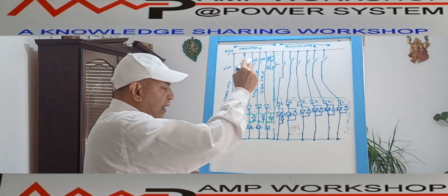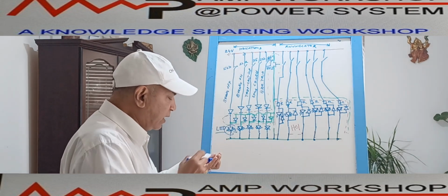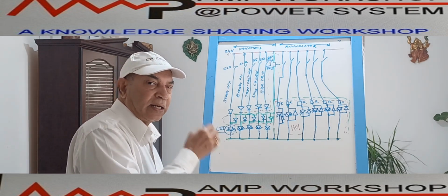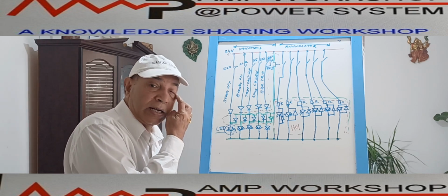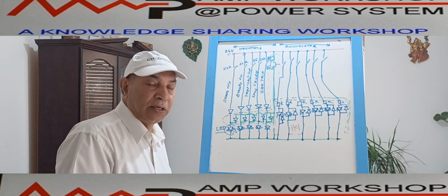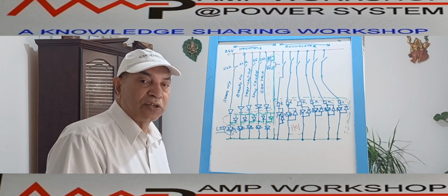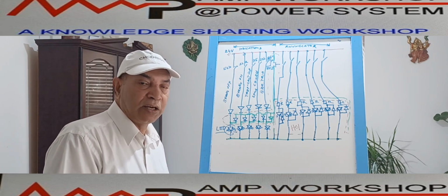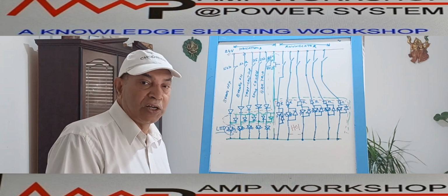Though it is an electrical circuit, in this circuit we do not inject the normal electrical control voltage which we have seen in the closing circuit, tripping circuit, and auxiliary relay circuit. We have used 120 volt DC.